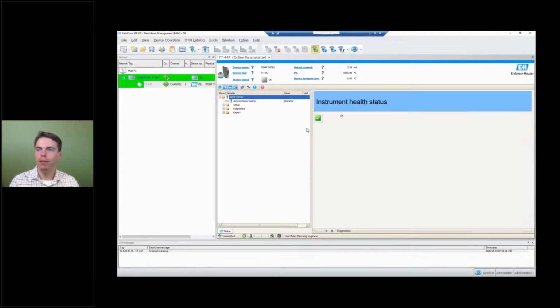it can take a couple of minutes until we see all data here. So you see it's already starting building up. We're connected to the temperature device. It's the Endress+Hauser temperature transmitter TMT82. Now I see the health status here, it's okay, and I can start doing diagnostics, troubleshooting, configuration, change measuring ranges, whatever I like to do with that device. And it's just one fingertip.